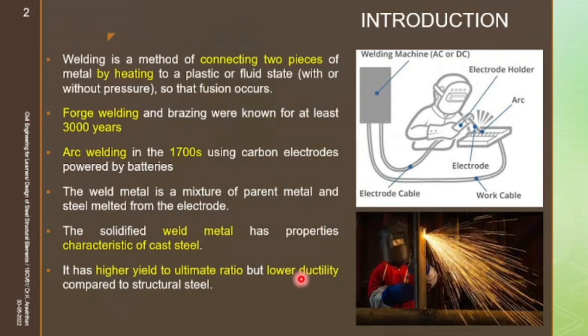You cannot stretch that welding material. You can stretch the member, which is made of mild steel, and elongate it up to 20 to 25%, but you cannot elongate the welding material. It is much lesser in ductility, so it is very brittle. There are a number of connecting rods available according to your purpose. If the grade of the plate you are using is Fe410, you have to choose the specific material for connecting that. So you have a wide variety of electrodes.